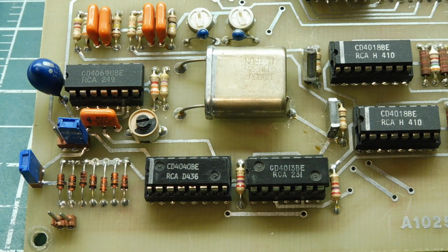Now if we want to run data down an AC coupled line like a telephone line or over a radio, we cannot send voltages over a radio, so we have to code them in a certain way, and we use FSK. So we use mark and space frequencies. So we use audio frequencies, so we'll have a high tone for the mark or a digital 1, and a space which will be a low tone which will be a digital 0. Now we could send these audio signals over a radio, and that will be our digital 0 and 1s.